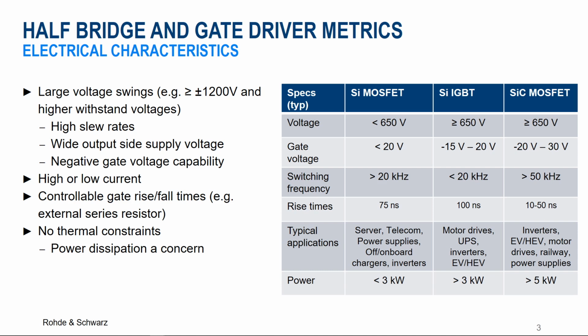Silicon carbide MOSFETs, while similar to silicon MOSFETs, have properties that allow them to operate at the same high power levels as IGBTs while still being able to switch at high frequencies. These properties translate into system benefits including higher power density, higher efficiency, and lower power dissipation.